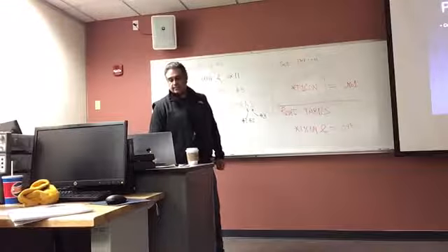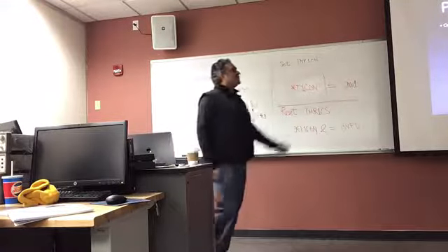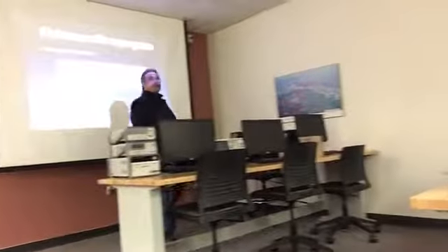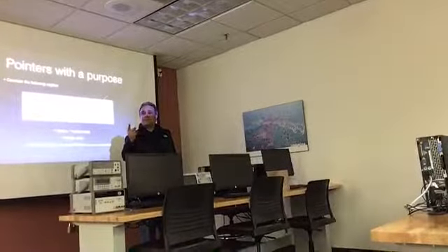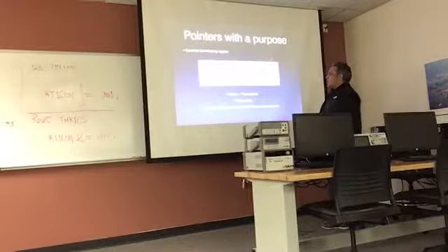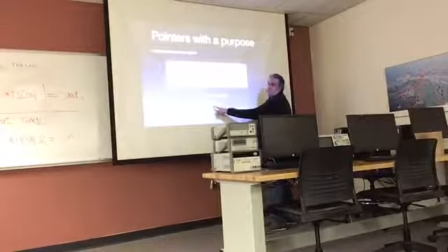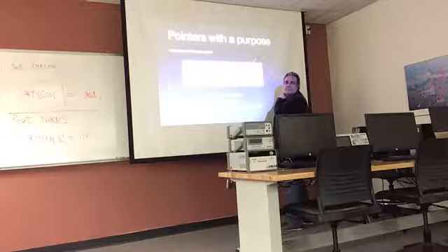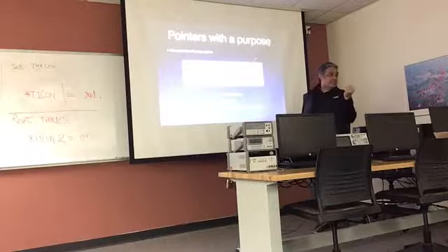So here's the answer. Now there's a little note. This is just the same slide as before. I just put the answers in there. But there is a problem with this, right? So there is a big problem. The problem is this. When I look at the instruction itself, it doesn't tell me that it's messing with the circuit called TMR1CS. It really doesn't say it explicitly.